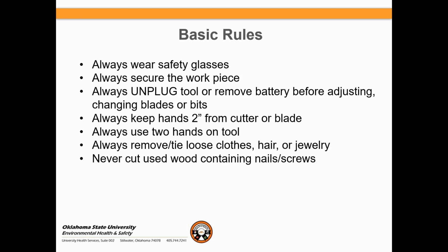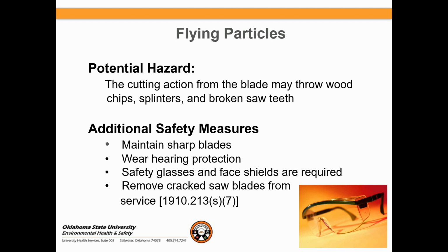There are some very basic rules anytime you're dealing with any type of equipment, particularly in the woodworking industry. Always wear safety glasses. Always secure the work piece. Always unplug the tool or remove the battery before adjusting, changing blades, or even the bits. Always keep two hands 2 inches from the cutter or even the blade itself, and always use two hands on tools. Always remove ties, loose clothing, hair, or even jewelry. Never cut used wood containing nails or screws. Just basic safety rules to consider there.